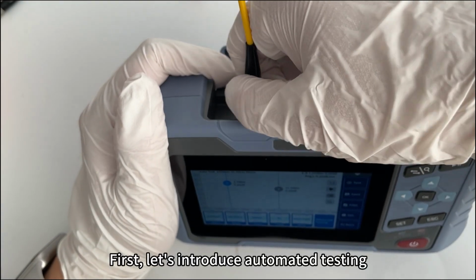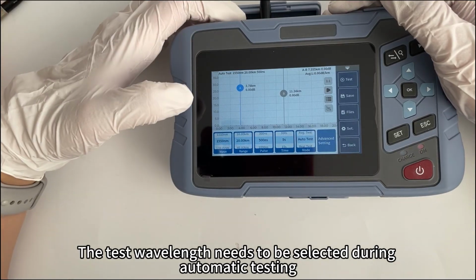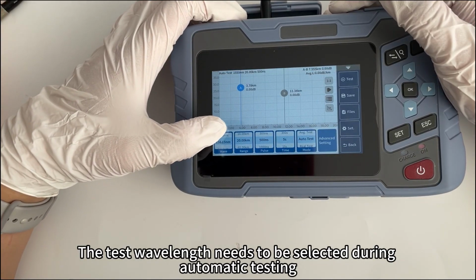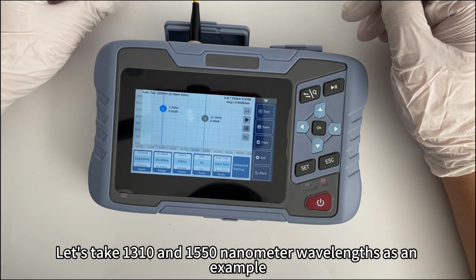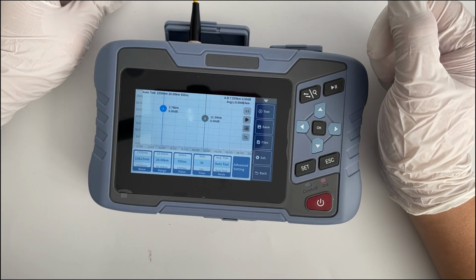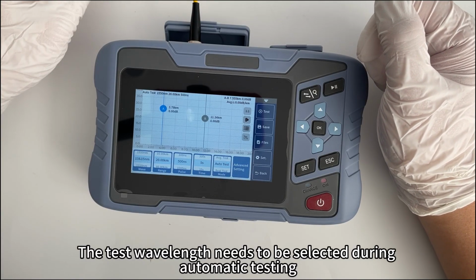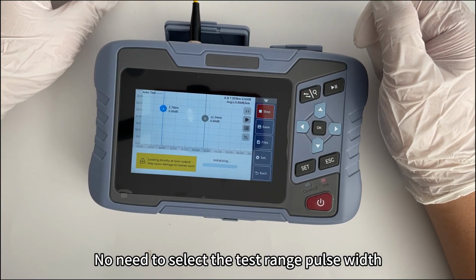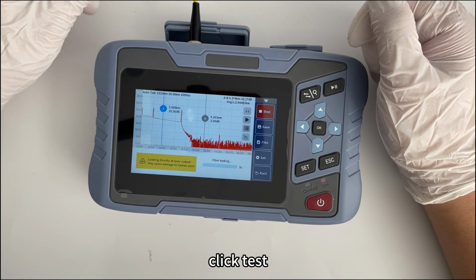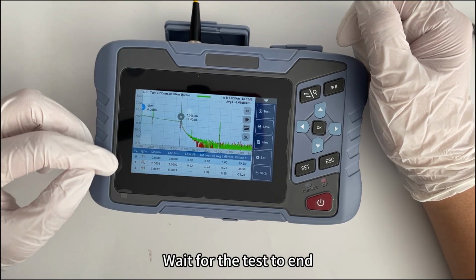First, let's introduce automated testing. The test wavelength needs to be selected during automatic testing. Let's take 1310 and 1550 nanometer wavelengths as an example. There is no need to select the test range or pulse width. Click Test. Waiting for the test to end.